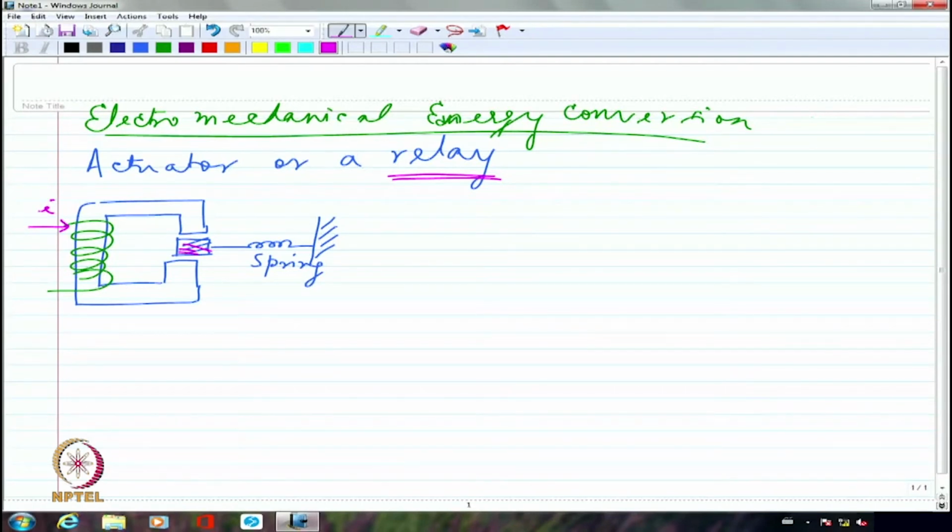So the moment it senses an overcurrent, it should immediately open up some switch. So that is what happens in our homes also in terms of many circuit breakers. You might have seen in the mains box, the circuit breakers generally act as soon as there is an overcurrent. So if there is a short circuit sensed in any of the rooms or any of the loads, immediately it will open out. So what happens there is also generally a relay or actuator mechanism.